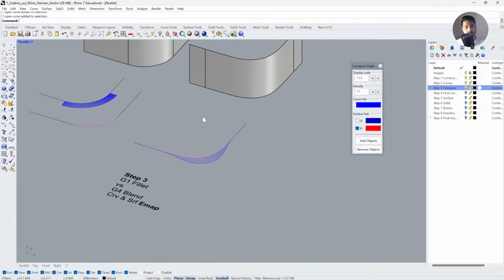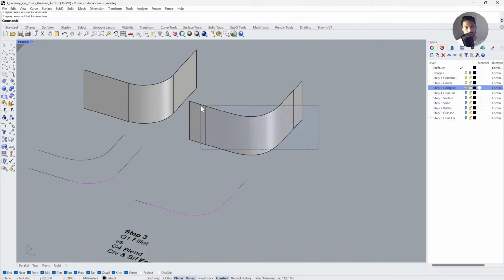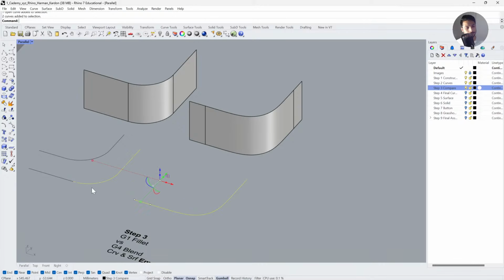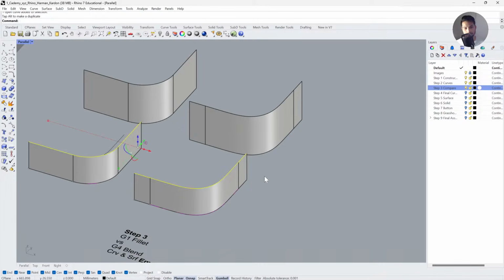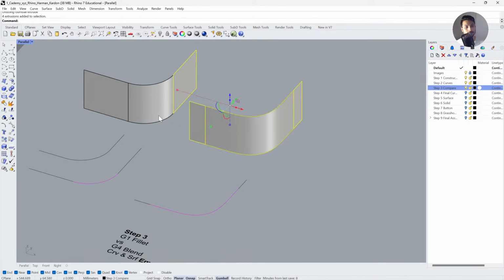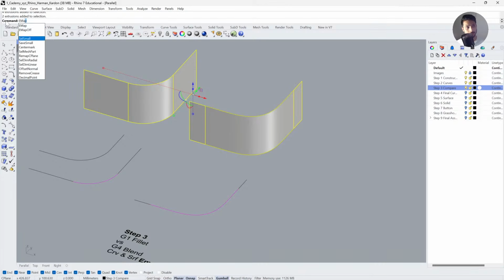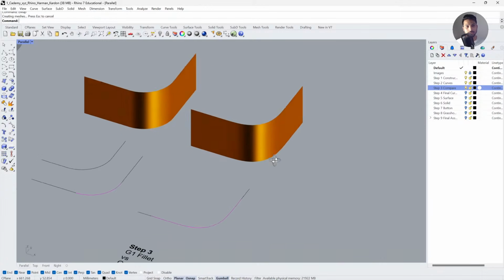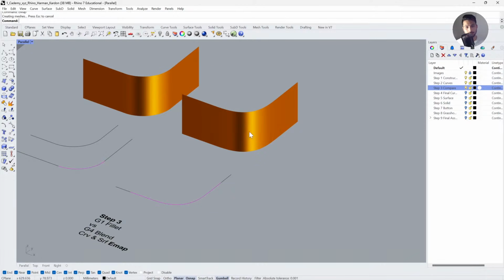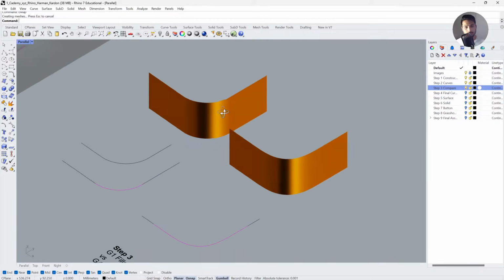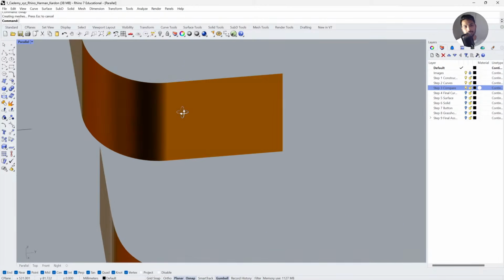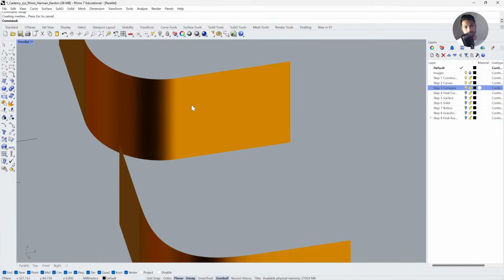So what this translates into is when you check these surfaces made from these curves, say if you extrude it, right, so you convert them into surfaces, and you run something like EMAP, which is some kind of environment analysis, you can see the reflection that these two geometries will create. So here, as we are changing the curvature abruptly, you will see a sharp highlight, as you can see here.